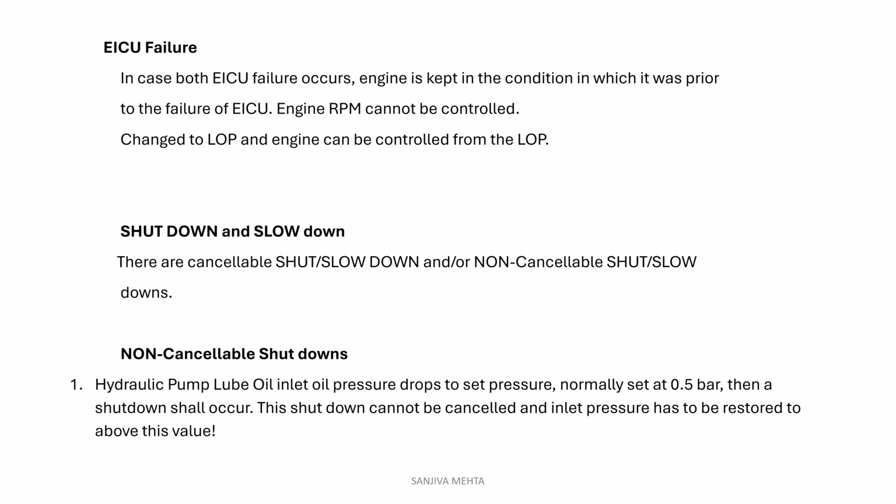That means sensors are fitted, a pressure transmitter. So the engine will stop because no lube oil is available to the hydraulic pump. This shutdown cannot be cancelled. Naturally, this is non-cancelable. No hydraulic oil, how to run the engine? Engine cannot run, so naturally shutdown will occur.